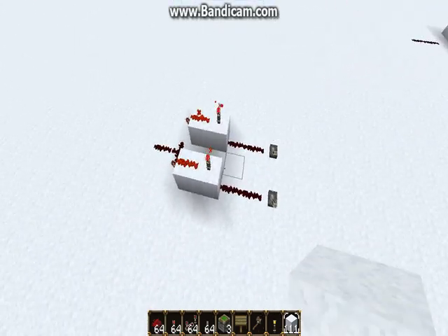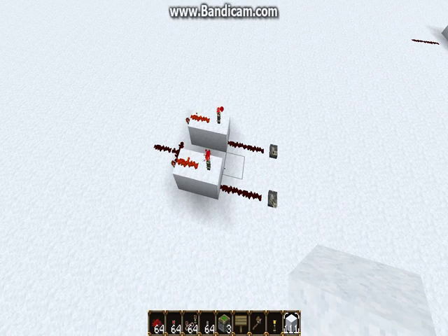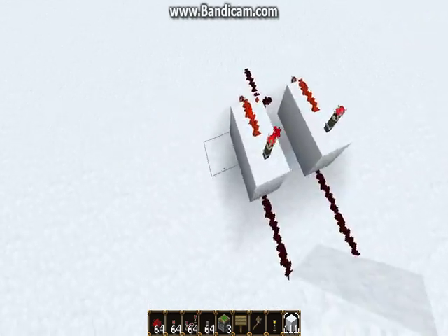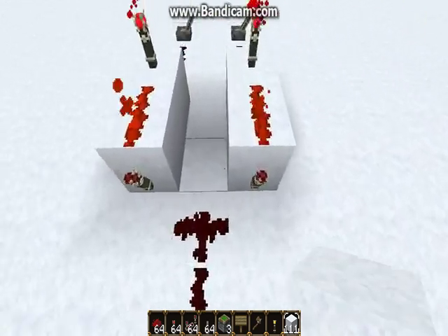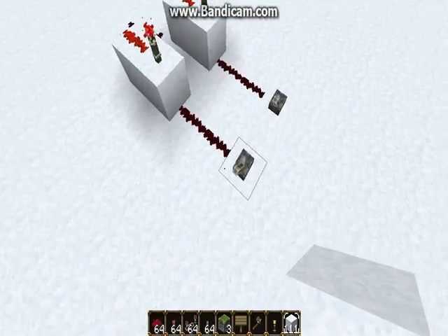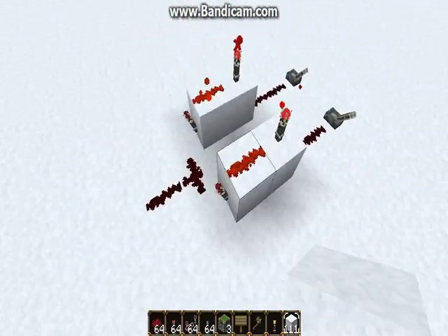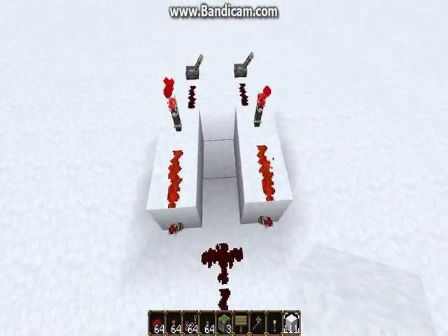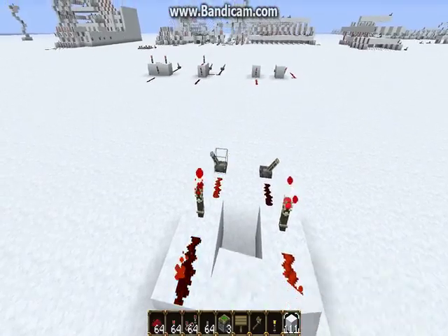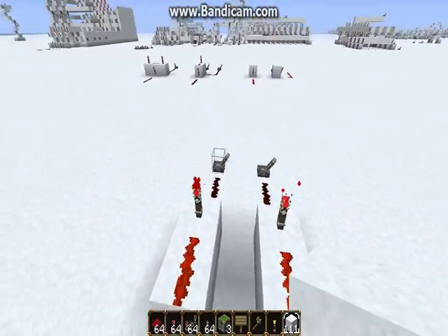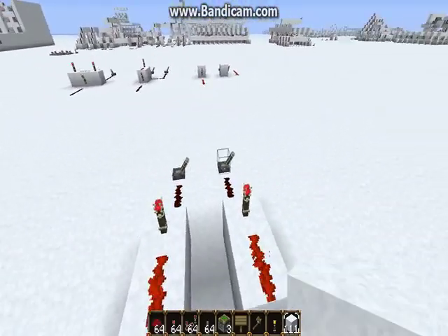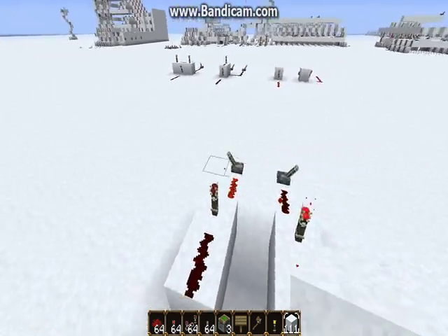So, how do we make this into an XOR gate? Well, there is only one difference between this and an OR gate. So a good place to start is to look at the desired output and the desired input in relation to that output. So first let's look at the desired output. In this output, if I flip through some other different inputs, there's only one thing that remains consistent.